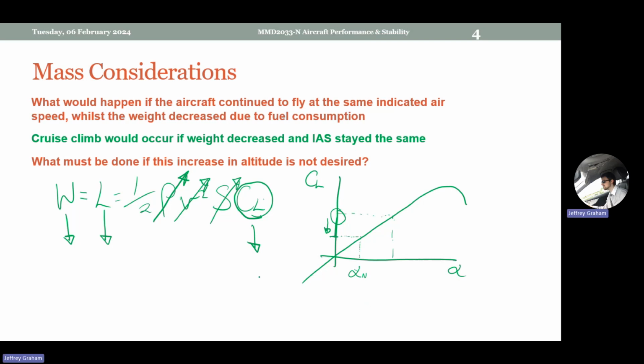Now, if we lower the angle of attack of the aircraft, it also often results in an increase in the velocity if we don't do anything. So the pilot has to do two things here: drop the nose of the aircraft to reduce the angle of attack, and pull back on the thrust levers, because the velocity otherwise would start to climb due to the lower angles involved.